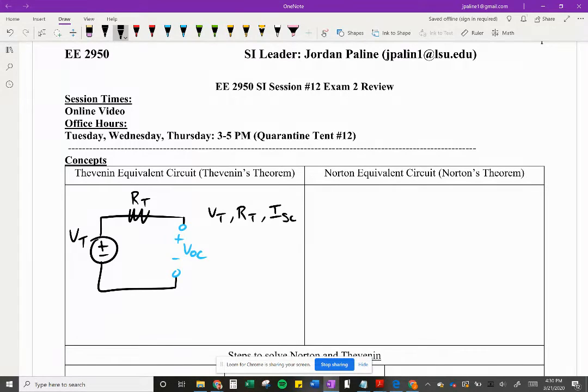and I short circuit, where the short circuit is the current that would be induced if we put in a wire right there, because current can't travel without a closed wire. Okay. And how these are related, we have VThev is equal to I short circuit R Thevenin, so just our Ohm's law equation.